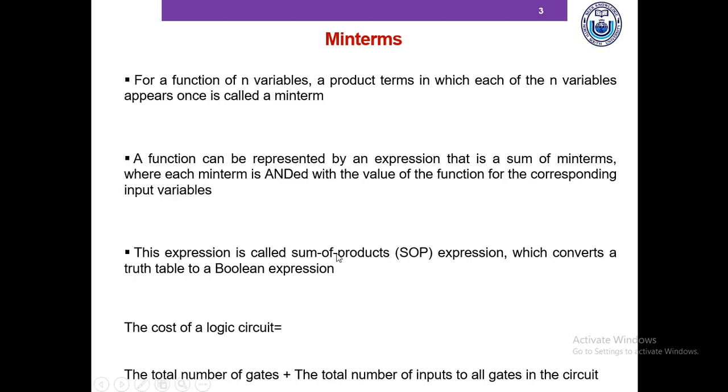Okay, so what are minterms good for? A logic expression or function can be represented by an expression that is a sum of minterms, where each minterm is ANDed with the value of the function for the corresponding input variables. This leads to an expression called a sum of products, or SOP, expression, which converts a truth table to a Boolean expression. So minterms are used to synthesize a truth table into a logic circuit.